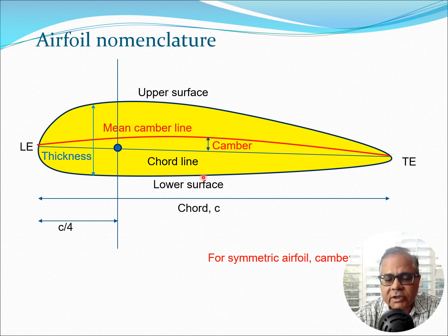It's essentially the deviation which the airfoil has from a symmetric cross section. So in case we have a symmetric airfoil, the camber is going to be 0. That's something to keep in mind, that certain aircraft, for example, helicopter rotor blades, essentially use a symmetric cross section there. But in general, for many aircraft, you will have a cambered airfoil.